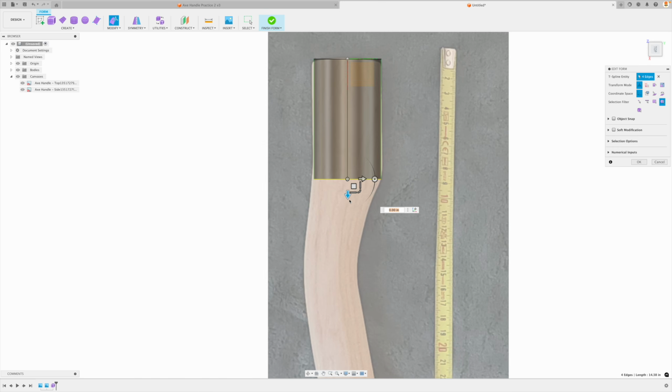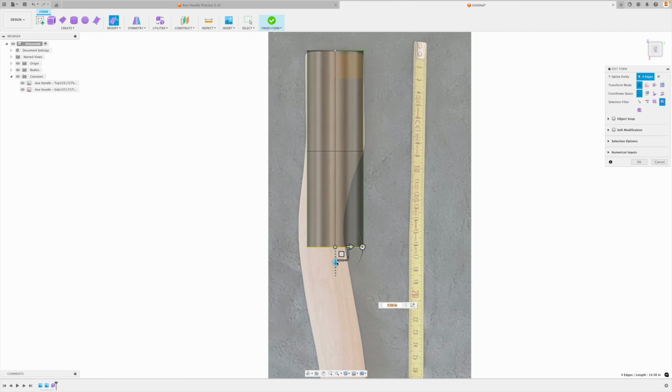So let's just create all these groups of faces all the way down our part, all the way down our axe handle. And the way we do that is you hold down Alt. So Option on Mac, Alt on Windows. And as soon as we do that, you can see as soon as we grab the arrow, now we've got a second group. I'm going to pull this approximately to where the next change is going to happen, where the path of the arcs kind of makes this change. And don't worry about placing it perfectly.